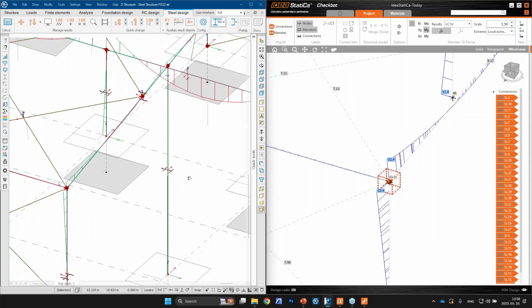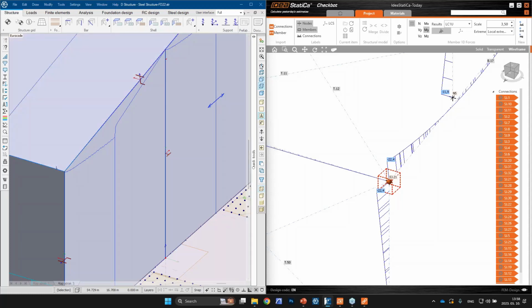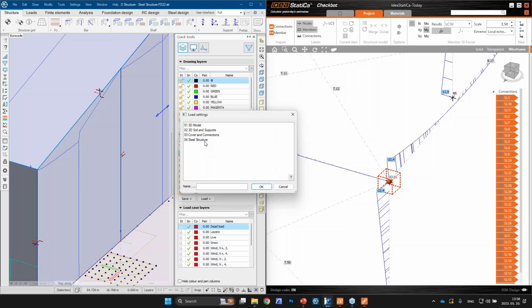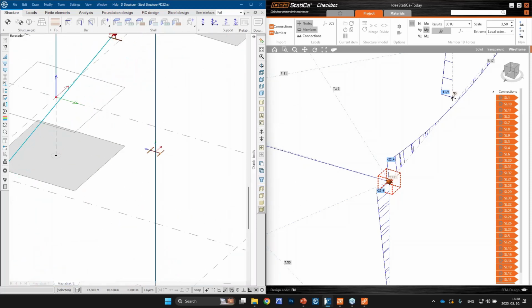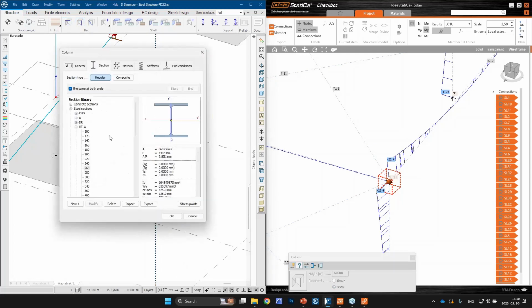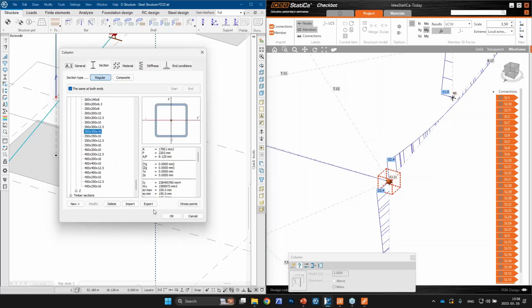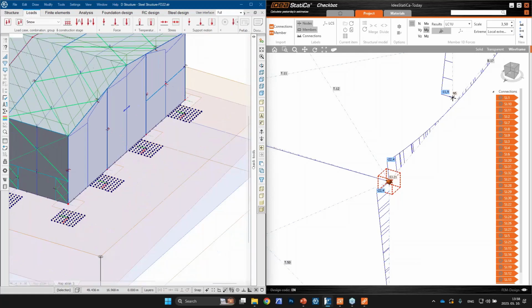So if I go back to FEM-Design, and for example, I change, first I hide the colors, I show you only the steel structure. So if I select, for example, a column and modify the cross-section of this from I-shape to a closed one, I search for that here, I check this one, and I also modify, for example, the loads.